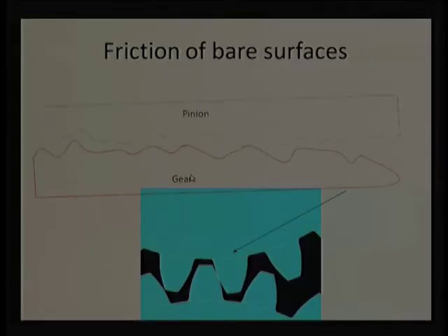Now, this can be demonstrated. Why is there friction? We are able to see there are some asperities. Whenever there is a mechanical contact under load condition, there is a possibility of deformation of the surface, and because of the asperities, there will be interlocking, and this interlocking may be based on just abrasion or on adhesion, the cold welding. In particularly dry surfaces, cold welding is a predominant phenomenon. Coefficient of friction majorly occurs because of the adhesion, the cold weld of asperities, and we need to reduce it as low as possible.